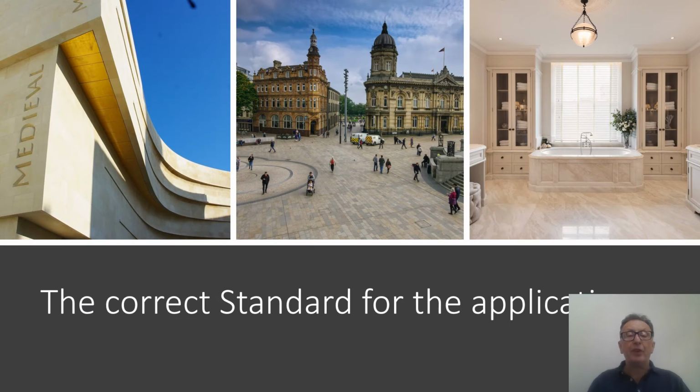It's important that the correct standard is adopted for the correct application of the stone. So whether it's being used as thin stone cladding, as more traditional masonry, as paving, or as internal flooring, ensure that the correct standard is adopted and followed, and this will give advice and guidance on testing characteristics and performance.